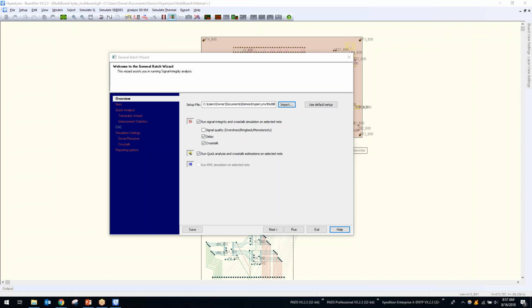Okay. Angelica, I see that you're asking, if I build a PCB with SPICE VHDL models, do I need to change all my models to IBIS? We do have the ability to simulate with SPICE. VHDL within HyperLynx isn't going to be supported. You might need to look into getting some IBIS models for those components.